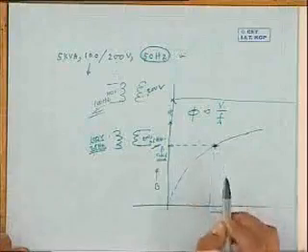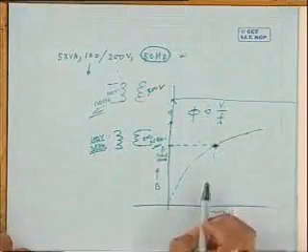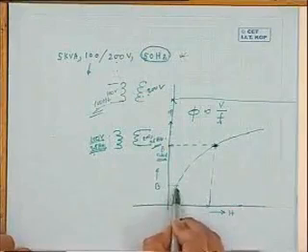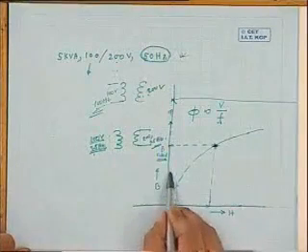See, in low frequency operation, one should be very careful about the operation of the transformer, because the magnetizing current that it will draw from the supply will be quite high, because the initial operating point corresponding to rated condition is generally at the knee point.